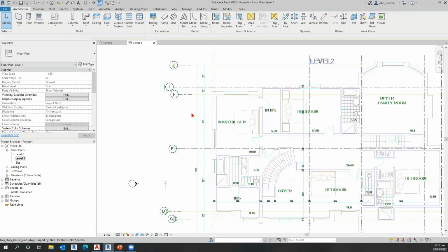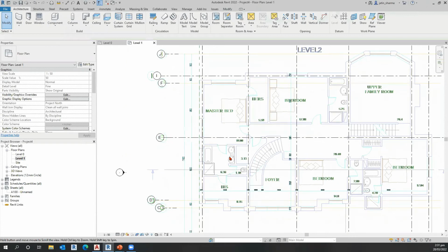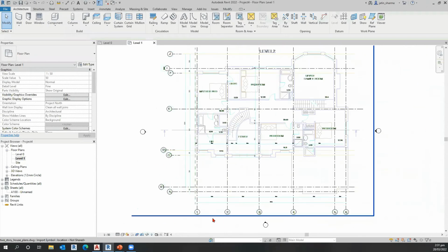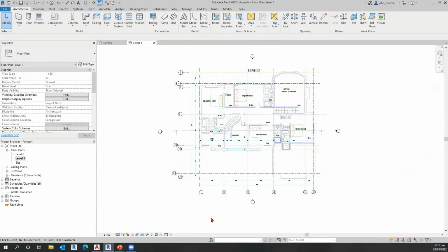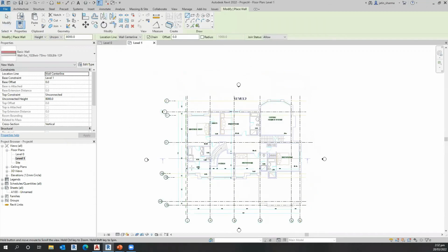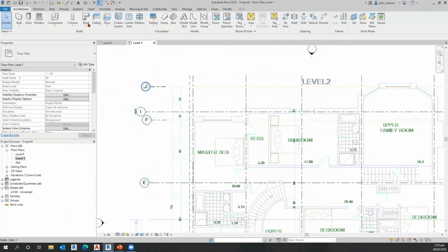The next step here is I would just begin drawing walls and windows and doors and start fleshing out this model. We've only got so much time, so I'm going to step back for a second and move on to our next workflow. But essentially, our DWG is now in our Revit, and all that's left for us to do is continue creating walls. You can go up to the architecture tab here, create walls, and this would connect back to your DWG. And similarly, doors, windows, all those components you can start creating.